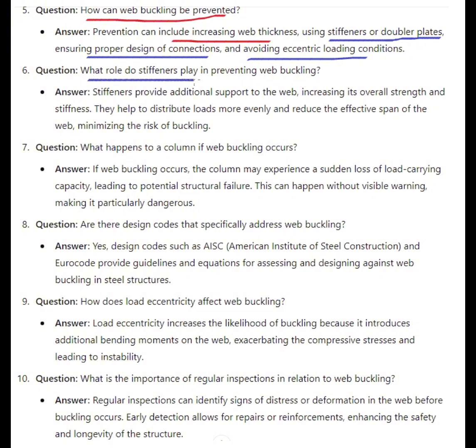What role do stiffeners play in preventing web buckling? Stiffeners provide additional support to the web, increasing its overall strength and stiffness. They help to distribute the loads more evenly and reduce the effective span of the web, minimizing the risk of buckling.